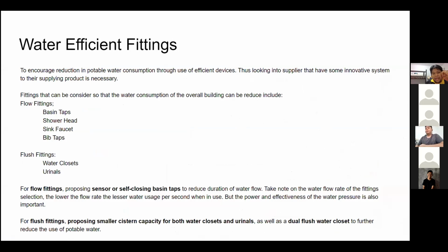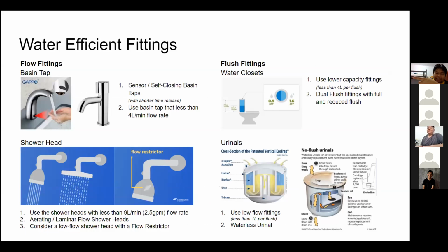Right now, if you look at the BQ, all of our water fittings are actually already water efficient. The problem is, there are a couple of problems. One is the tap in the toilets: when you press it, it stays on for too long. I already studied some of the BQ. Another is the flushing system for the toilets: when you press the button, too much water comes out.